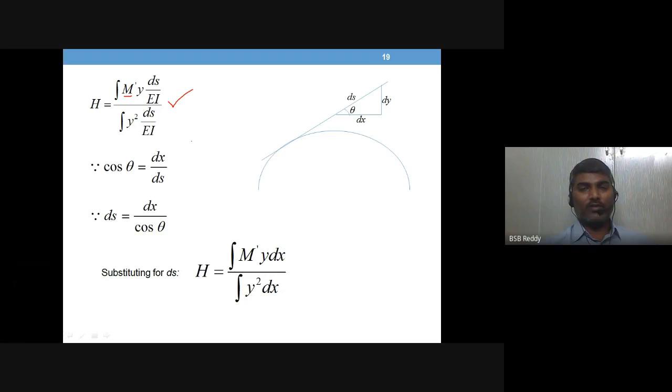So to work with parabola, Cartesian system is comfortable. So we need not change the Cartesian coordinate system available in the equations. For example, m dash you write in terms of x, so let it be there. And similarly, y you have to convert using the relation between x and y. You have to convert into the integrand term that you get by changing this ds. Okay, so what do you write for ds in case of parabolic arches?